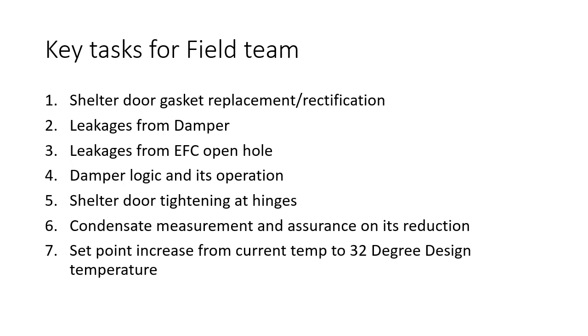You can buy foam gasket from any local hardware shop and fix your leakages. Even leakages from the damper and EFC can also be arrested by using silicone or foam-based gasket.